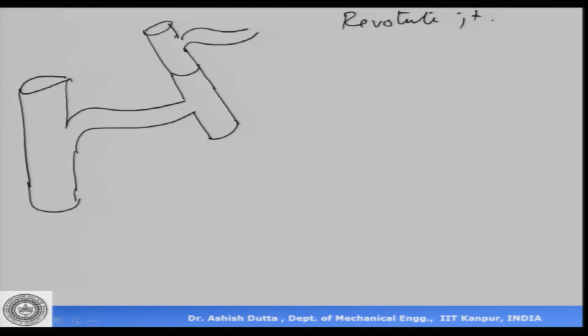Now I am going to assign the axes as per DH notation. The first axis is a revolute axis, so there is one more here on this side, right. It's like a tree branch going from one link to the other link, but they all have funny shapes. So this is my z axis, which I first put as z. Let me call this z i minus 1. Now an axis can point upward or it can point downward towards infinity, because an axis is a line, right, and it goes from plus infinity to minus infinity.